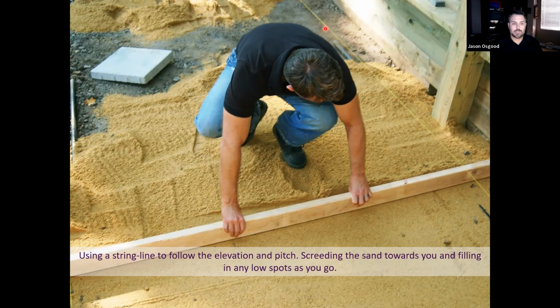And he's got one on the left-hand side as well. And what he'll do is he'll pull this board along the string line to get him the proper level that he needs for his sand. It's a really nice, easy way to do this.